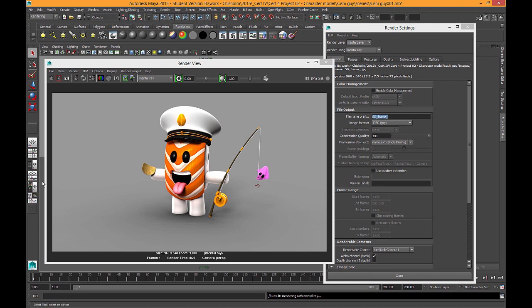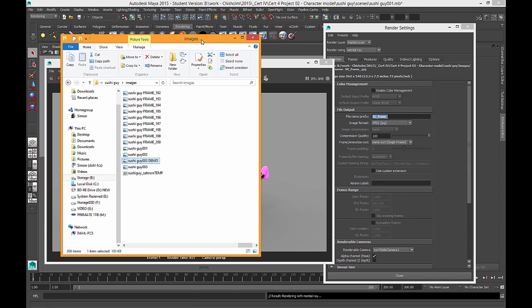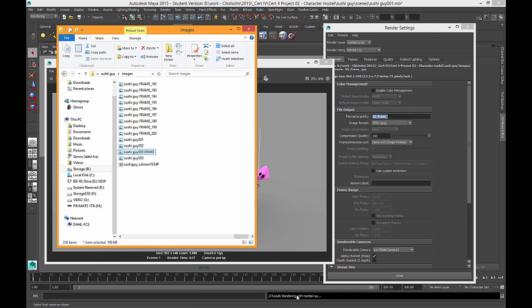You'll see down here it'll say rendering with Mental Ray, so it's exporting the scene file into Mental Ray, and it'll start generating the image in a second. There it goes, so it's starting to render now. 35% done. Technically it should use this file name, sg_frame_, and it should be a JPEG. We're now at 65% finished, 70. Keep in mind, if you're rendering an animated sequence, this percentage is for the single frame that it's rendering. Okay, so that just finished.